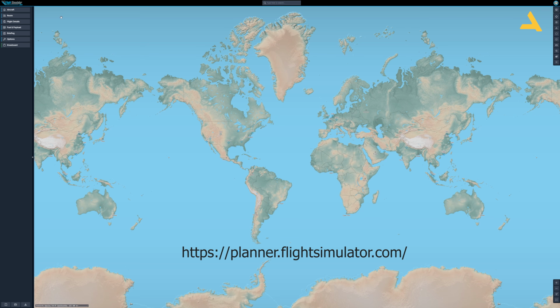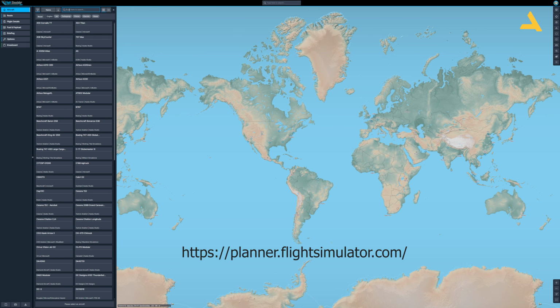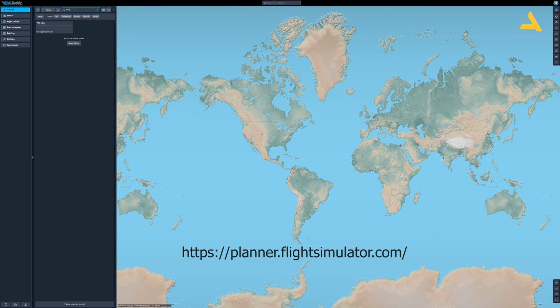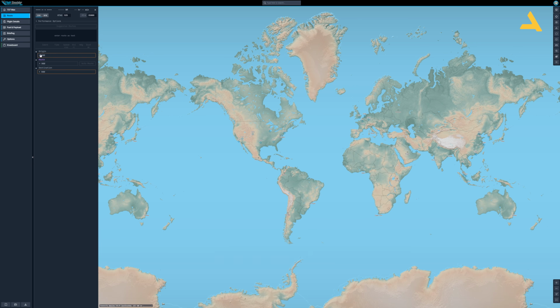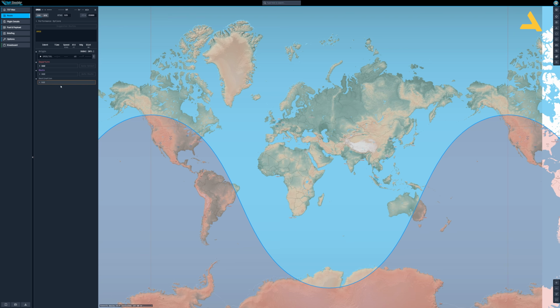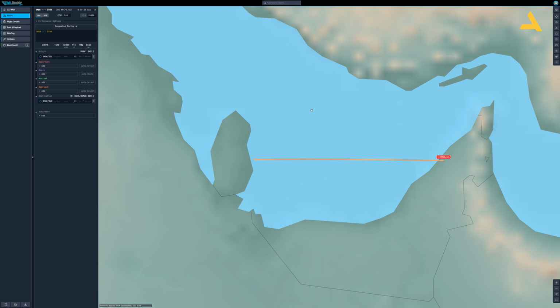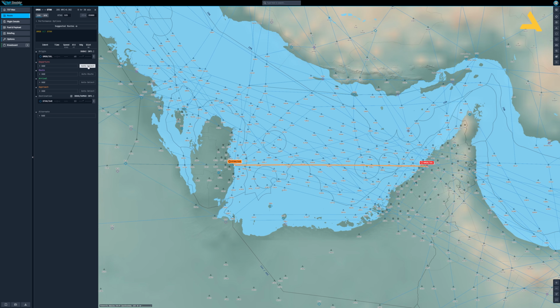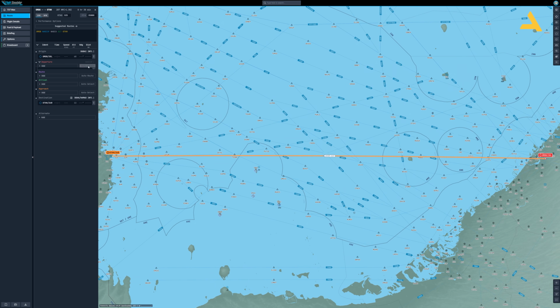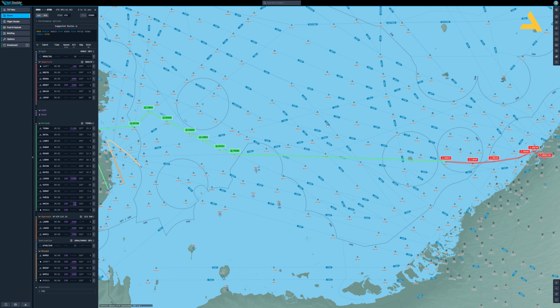First of all, let's select the aircraft, and the aircraft is 737. You need to select the aircraft because you have to do this fuel calculation over here. Then select the route. So for the origin, it's Dubai. I'm doing this flight from Dubai to Qatar. And for Qatar it's OTHH, which is Hamad International Airport. A short flight. And let's auto-select the departure and auto-select the route.